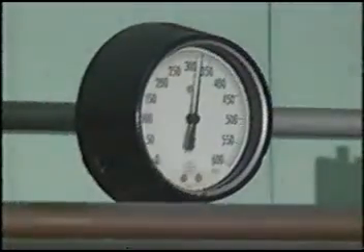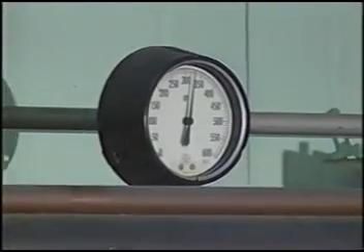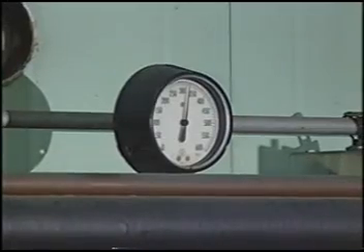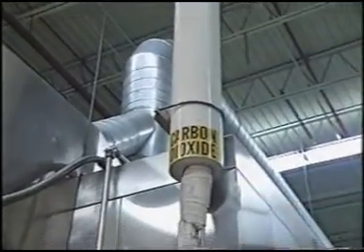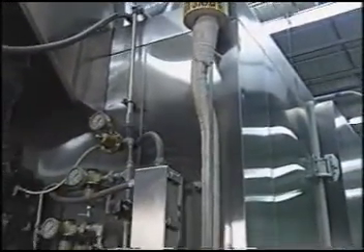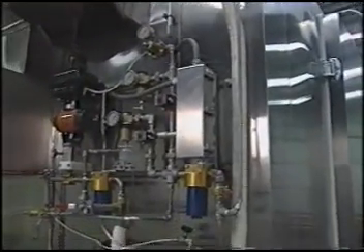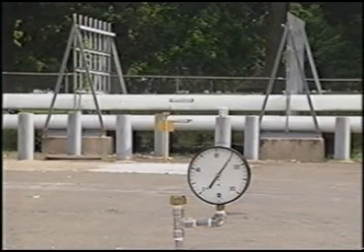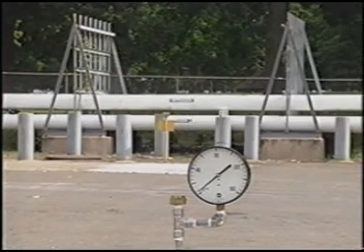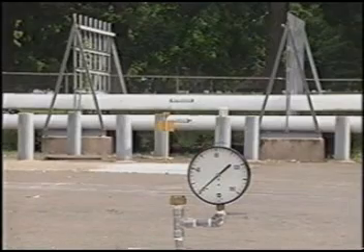A second potential hazard to guard against is overpressurization. Any pressurized gas can be dangerous, even air, but it's especially important to protect against overpressurizing carbon dioxide. For example, carbon dioxide used for refrigeration is delivered as a liquid by pipeline. By accidentally trapping this liquid between closed valves without safety reliefs, it will warm and expand. Without enough room for expansion, the pressure can rupture almost any distribution pipeline.